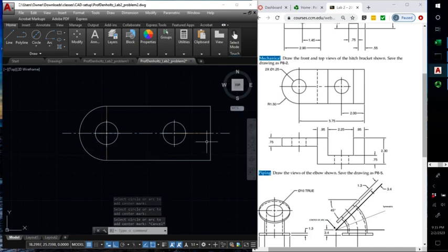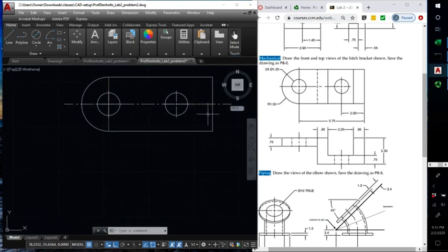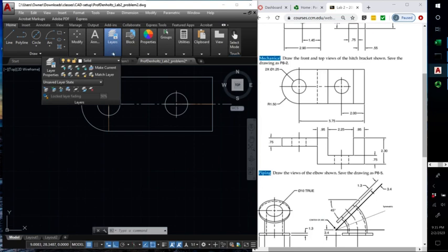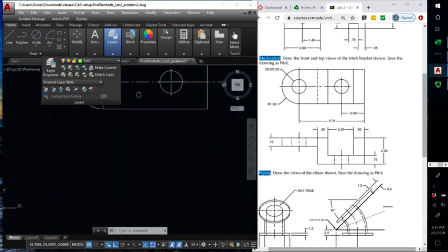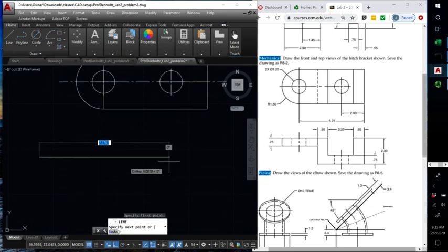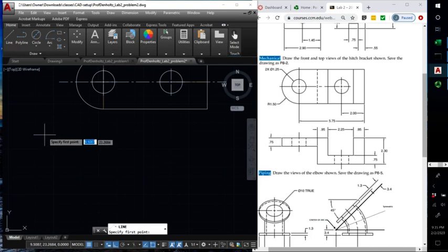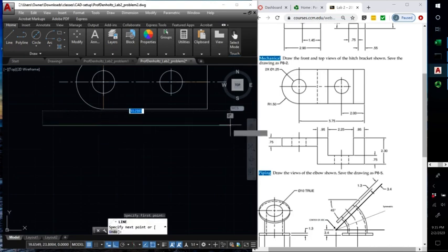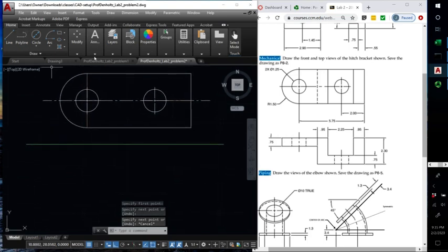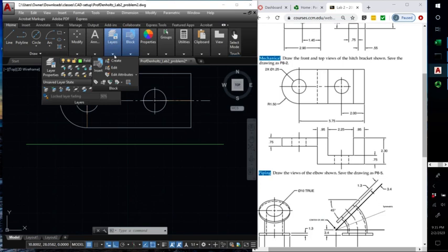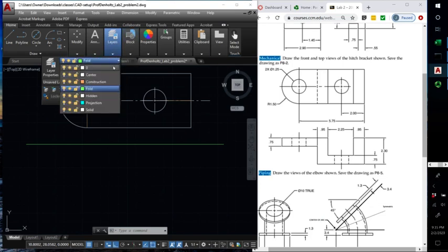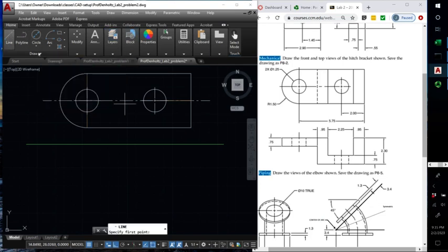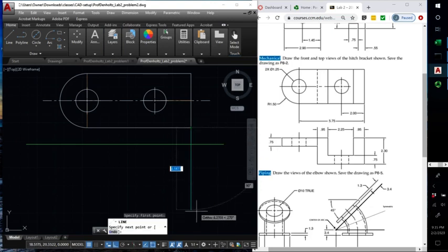Now I think we need to pivot down to the front view. So, all right, I'll draw in a fold line. So let's have a fold line over here. I'm going to make it a little bit closer just because my screen's kind of small. And let's start drawing some projection lines. So let's go over to projection, and let's just draw a handful of these lines.